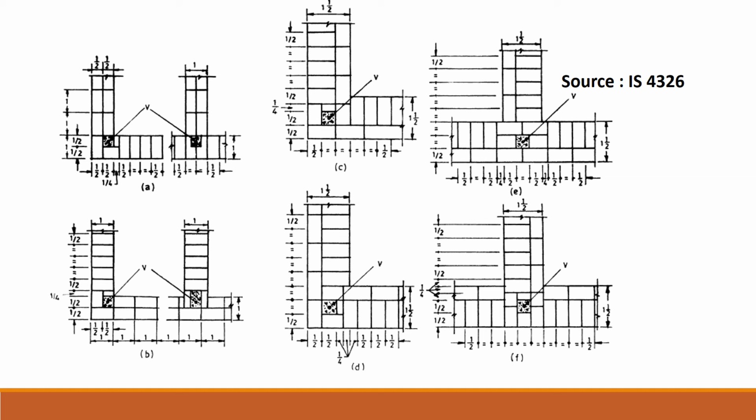Now one is the external and another is the internal partition, and both have different formations of vertical reinforcement. This is done so as to maintain the vertical joint between the brick walls, and further to also give strength to the corners of the walls. And in B, one can see that when header and stretcher courses are run, then the vertical reinforcement in a 1 brick thickness wall is provided in this fashion.